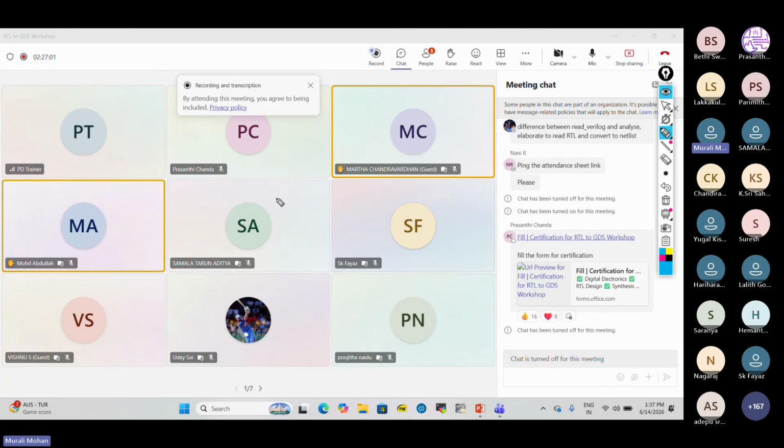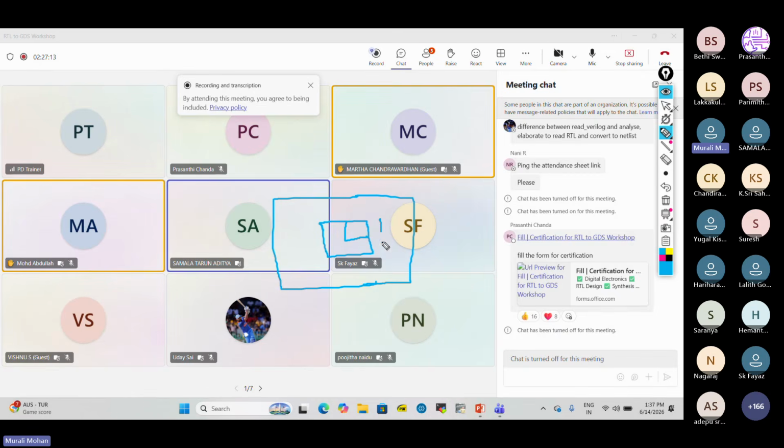See, for example, you can see the screen, right? Here this is your floor plan, and this is your core area. If you think there are two voltages, this is your VDD, this is your VSS, and this one you are going to call VDDL. The VDD is supposed to distribute power only to this block, where the VDDL is supposed to distribute power to this particular block.